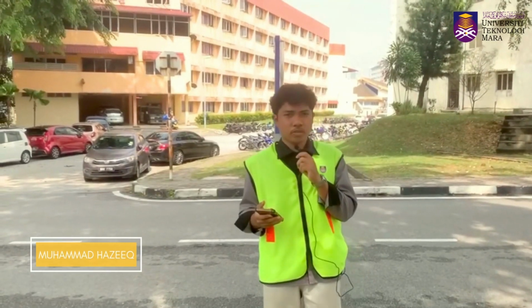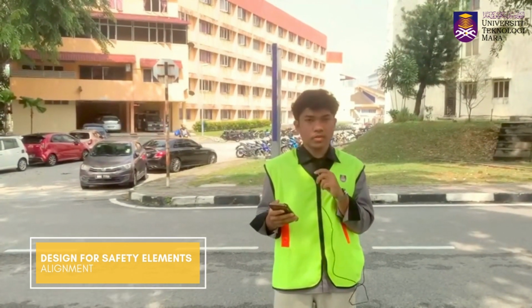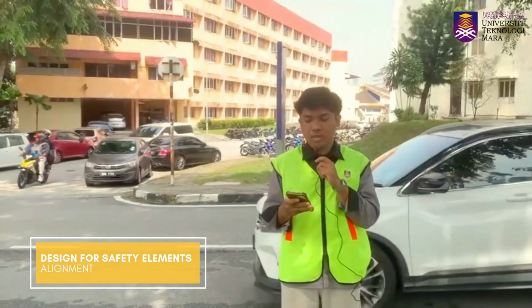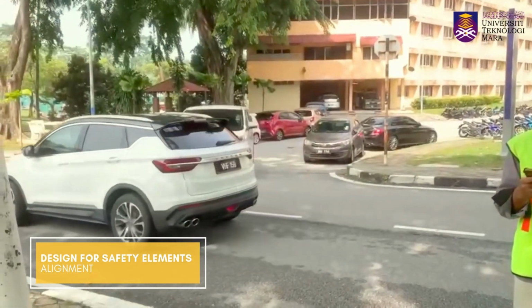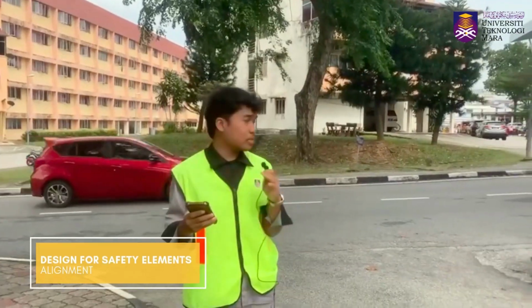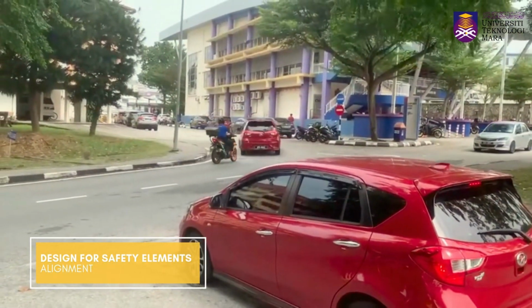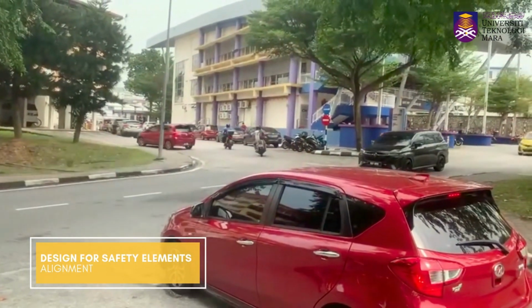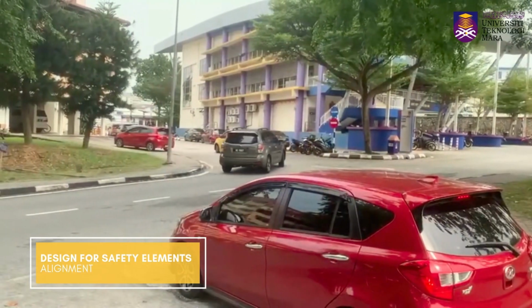Next, the problem that we encounter for this intersection is the alignment. As we can see here, for this junction, the cars who want to turn left will have limited space to turn. So the car will cross the opposite lane, which is dangerous for them and might cause accidents. The cars who want to turn left have limited space to turn, especially when the traffic volume is high. So the car will enter the opposite lane, which is dangerous and might cause a clash between cars.